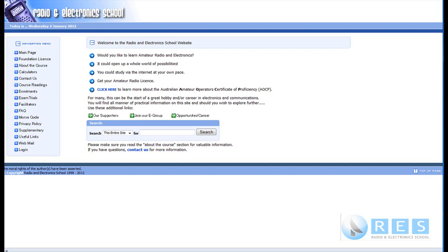If you want an amplifier to oscillate, you need positive feedback. If you don't want an amplifier to oscillate, you need negative feedback, and that process is called neutralization. Applying an equal amount of negative feedback to cancel out positive feedback is called neutralization, and radio amateurs do that with their power amplifiers in their transmitters all the time.